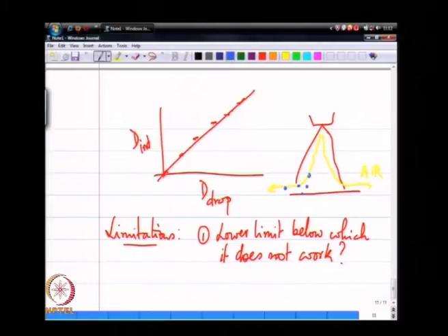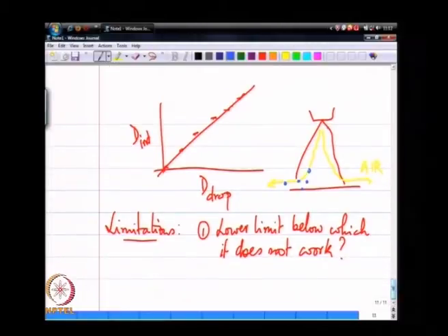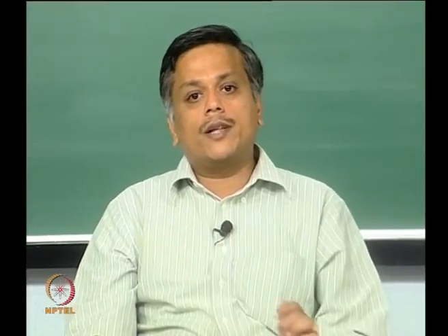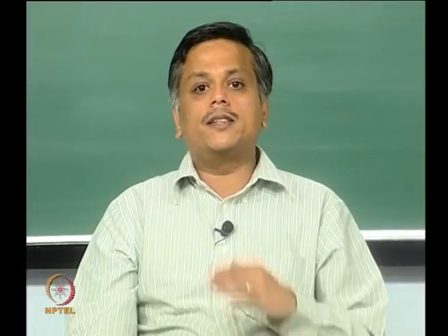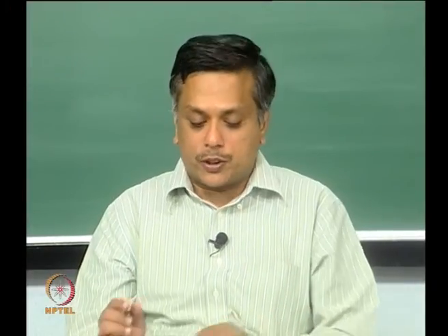Okay. This lower limit is one reason why you will only tend to overestimate the drop size. So, if you have some fine particles in your spray, those will not be measured by this, and so you will only tend to overestimate the drop size. So, you do have an upper bound. So, this provides an upper bound over the real drop size.